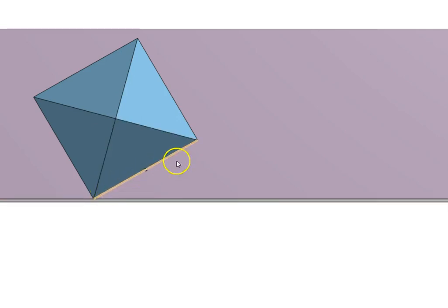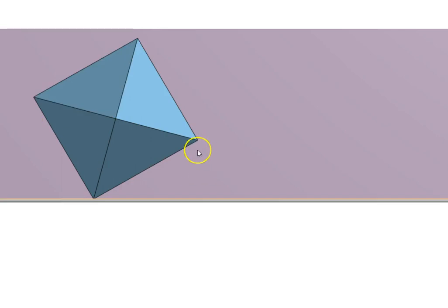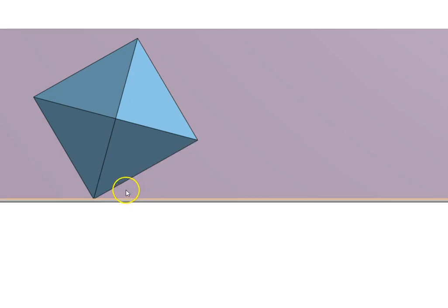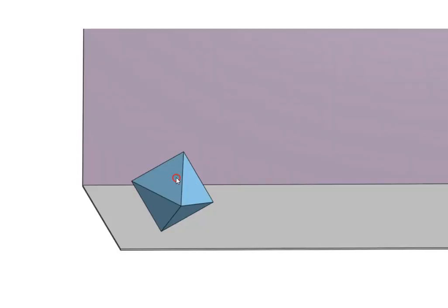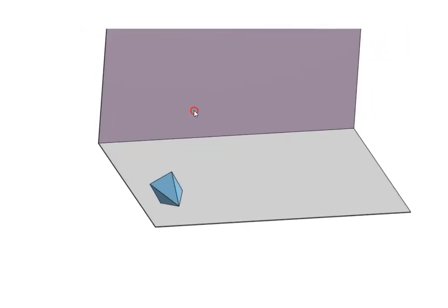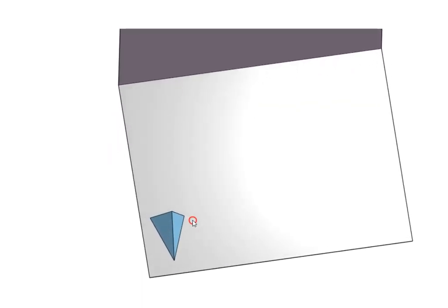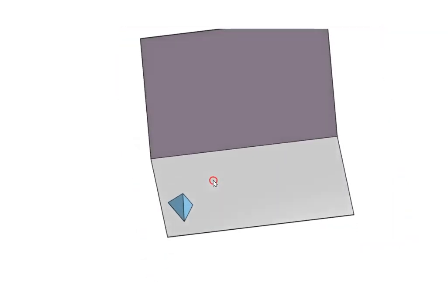So these two conditions have been satisfied. The side of the base containing this corner, which is either this or this, in this case we are taking this edge, which is at an angle of 30 degrees to HP. So that initial condition is solved. The next stage would be to tilt this solid with respect to VP at an angle of 60 degrees, so that the axis becomes inclined at 60 degrees, which is quite simple. You simply tilt this solid in either direction so that this axis becomes tilted with respect to VP, which is a straightforward solution.